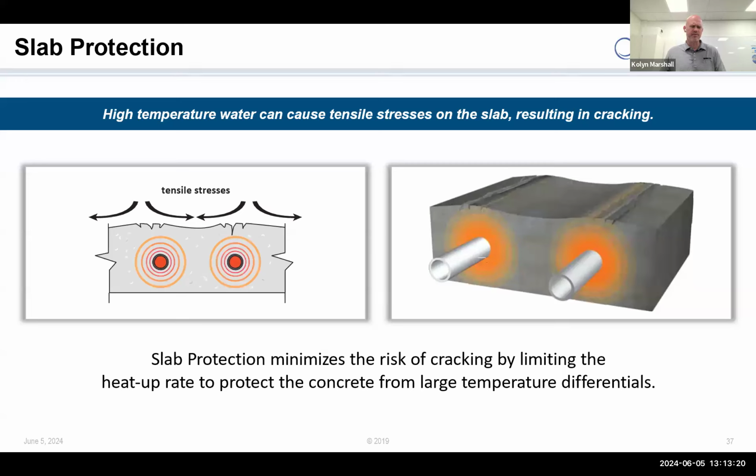The 150 came from old electric snowmelt systems that were installed in the 40s and 50s. Those systems went in without any control or regulation. It was literally a cable in the slab hooked to power, and that was it. When you flipped the switch, that wire got hot instantly everywhere, and it was an unregulated wire. So the wire temp could have easily been 250 degrees. And it was almost always placed fairly shallow in the concrete.